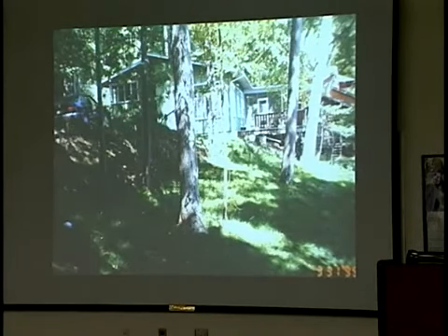The soils weren't too bad in this spot. When we started testing the soils, we didn't have to bring fill material in or build a cribbing area. And up in this embankment, the soils weren't too bad. A little concerned about leaving the trees, but we snaked the leach lines in between these trees. Given that we were concerned about the root matter, we put an inspection port right here on the line. Came down here, ran some more lines in this area.